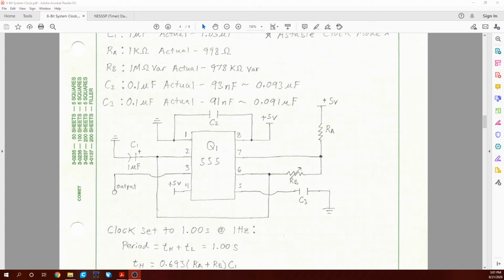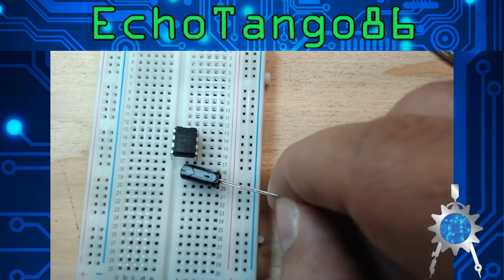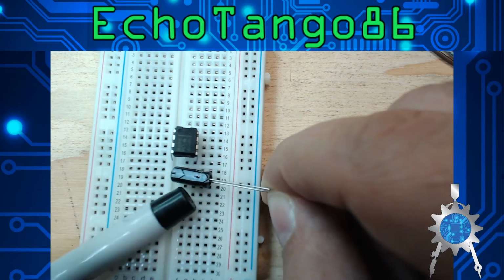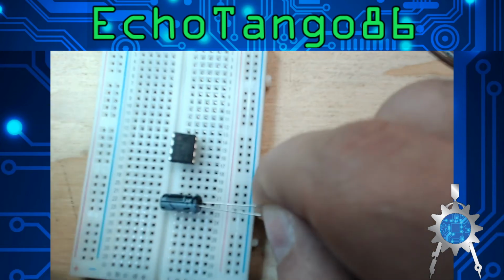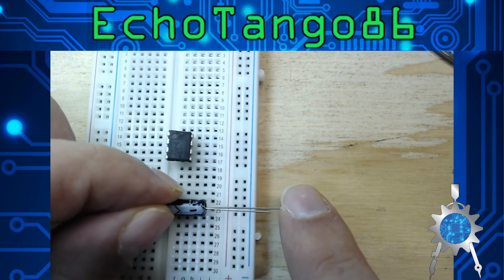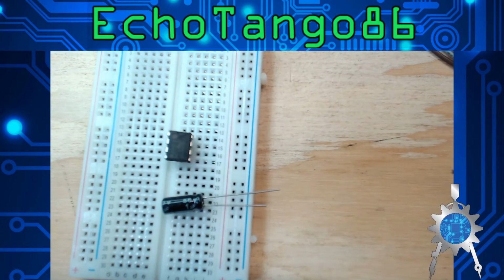And that's what one of these looks like. Microfarad. You see right there, it shows that it's a little negative on the gray. This side that's facing the camera right here tells you to make sure that this pin here, which is this one, is your negative side that goes to the ground. And they also made the positive lead longer. So you can tell the shorter one goes to ground, the longer one goes to positive, also known as cathode and anode, if you want to get scientific terms. Yeah, so you'll need one of those.